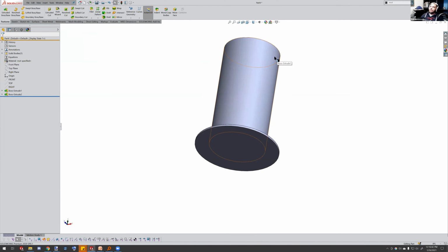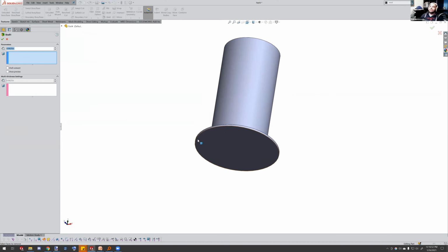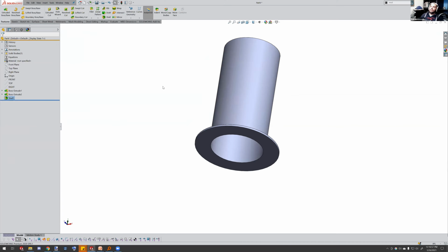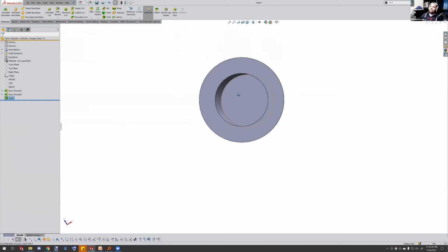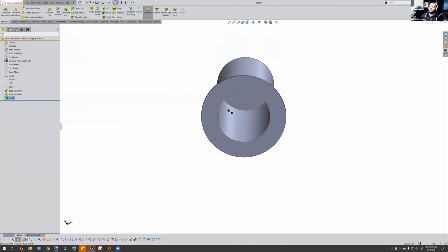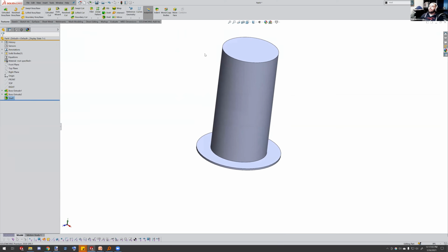Make an inner surface with a slightly smaller cylinder, and then turn all the inside stuff into air. In SolidWorks, that's this shell command here. You just turn something into a shell. And with just one click, you can see that the hat is now hollow.